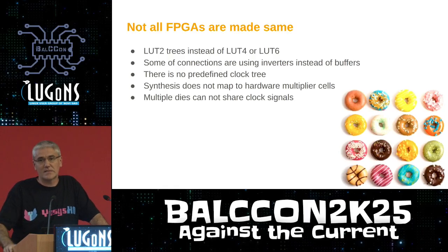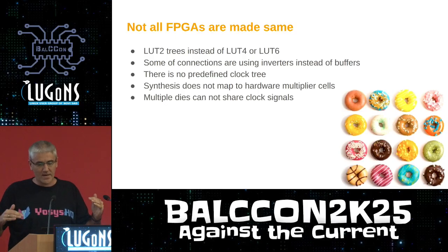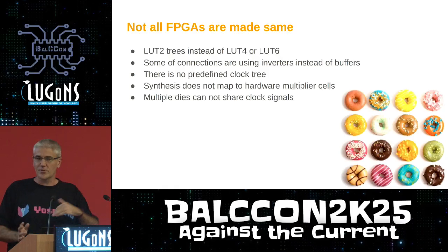I mean, it's amplifying the signal, but it also inverts the signal. And that was actually quite annoying, because a lot of time we spent on validating which parts are actually inverting and which are not. So some routes were and some were not.